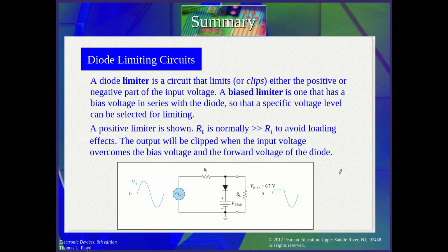So another circuit, the diode limiting. Diode limiting is a circuit of diodes that limit or cut some of the input. So it makes a threshold here. If the voltage is higher than this voltage, it makes a limitation, so it gives you output like this.